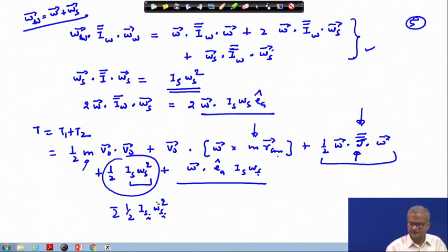This is the spin rate of the wheel. All the wheels can be rotated at different speeds with respect to the satellite, and that is required in order to control the system. Basically, in controlling, what is important is the rate of change of angular momentum of the wheel about its own axis. So this part is used for controlling the satellite attitude. Very soon we will get into the control topics also. Although we have fewer lectures, as far as possible I will try to cover it.